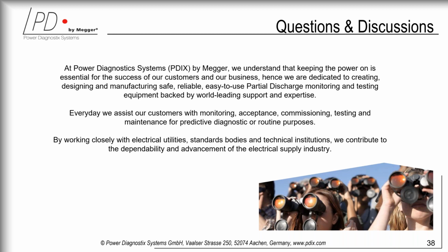I know that our North American customers may want to have DNP3. We are willing, based on a conversation, to evaluate what it will mean to install a DNP3 stack. But at the moment, the system supports 61850. I remember a project in Mexico many years back where we implemented DNP3, but that was one installation. So in principle, yes, we are flexible enough to find out if we can offer such an interface as well.